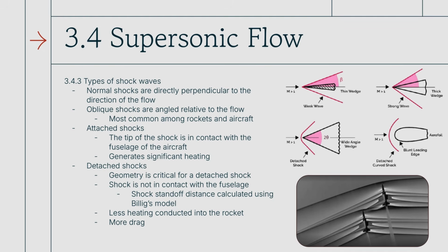Like the detached shockwave, the detached shock only occurs when the angle of your cone is greater than the angle of the shockwave. Yes. There's math involved. It's probably not 100% right what I said, but that's the gist of it.